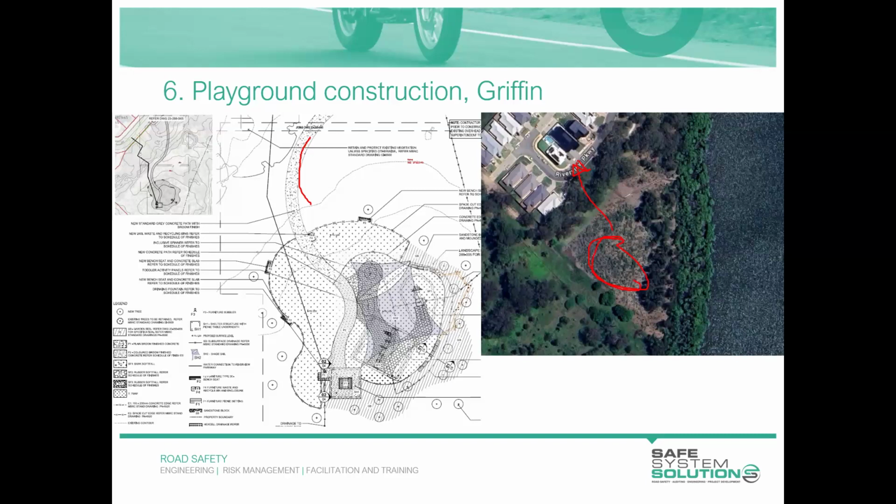With the embankment, it's the same, slip and fall, the fencing would at least reduce the fall. The other thing was the potential of landslip on the embankment. So we decided you have to have controls in place for proximity of working next to the embankment, and probably checking the stabilization of the embankment before any heavy machinery was put to use.